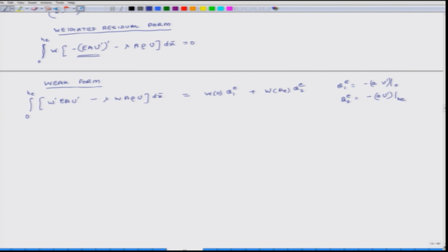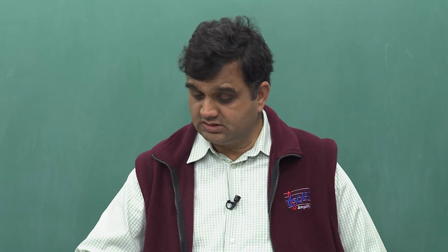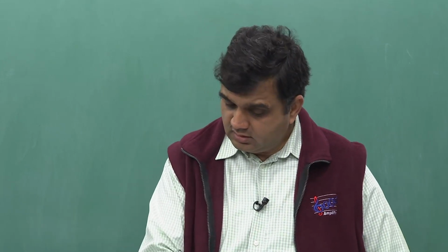Okay. At this stage, my next step is that I assume an interpolation function for u. So, u is equal to the summation of u_j and phi_j(x), and this is for the eth element, with j equals 1 to m, and in this case I am using m equal to 2 because I assume that it is a linear element. Also, my weight function equals phi_i for the eth element, which is the variation using principles of variational mechanics. This is nothing but it represents a variation in u.